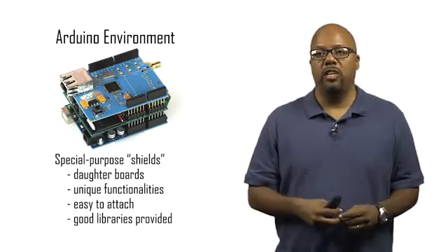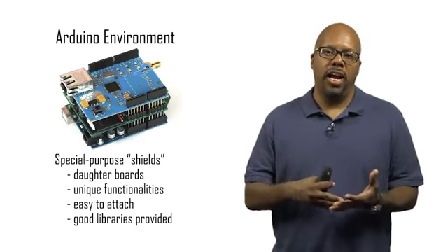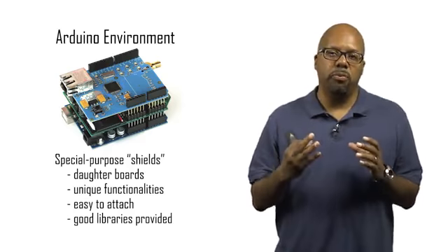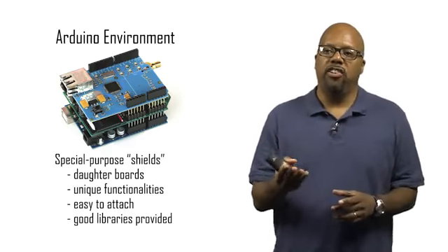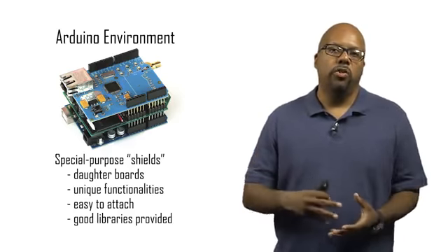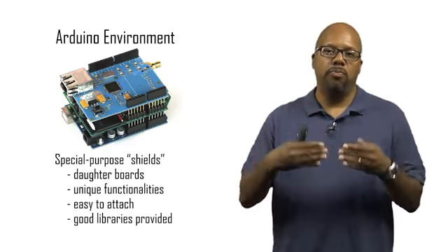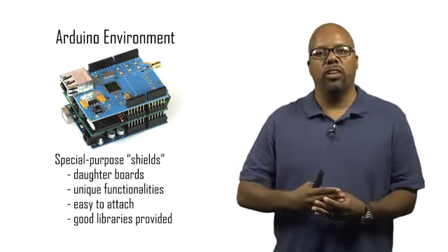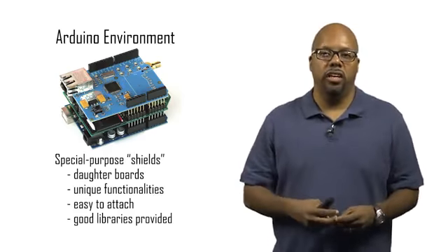The thing looks like it has 80 pins on the side. You got to wire all that up. It's a lot of wiring, and it's a lot of coding. But what happens with these shields is they basically pre-wire everything. So they give you a board, a little shield, which has the chip on there pre-wired. You take that board, you stack it on top of the Arduino. So it has pins going out underneath the board, and you stack it on top, it goes into the holes in the Arduino board.